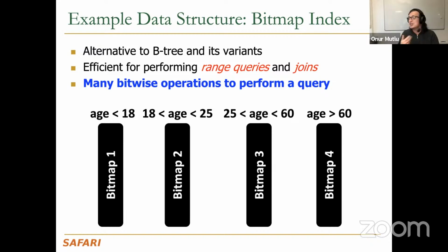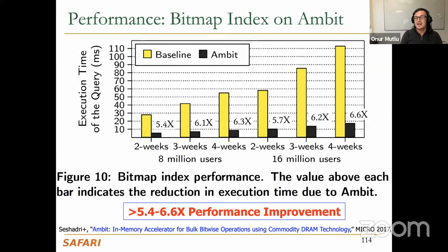And the predicate computation is essentially bulk bitwise computation in the entire bitmap. So you have a lot of bit level parallelism and a lot of bitmaps. And this is a very good fit for Ambit, for example. And Microsoft has designed a web search engine to operate in a similar manner, like these bitmaps. And the Ambit paper shows that you can actually improve the bitmap query performance significantly. This is end-to-end in simulation, of course, because clearly it's very difficult to manufacture this chip.